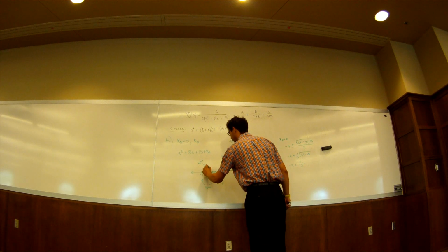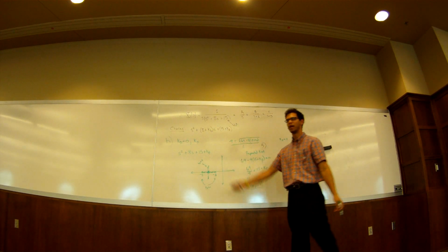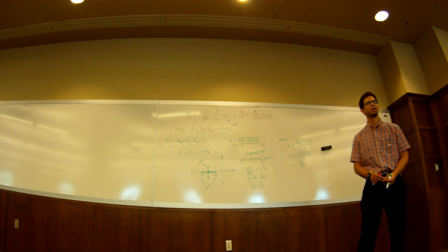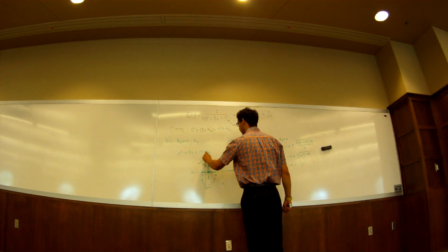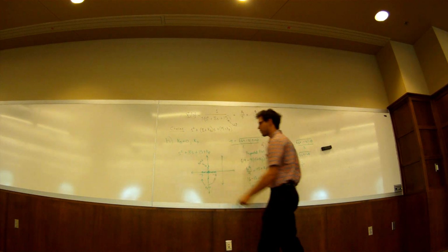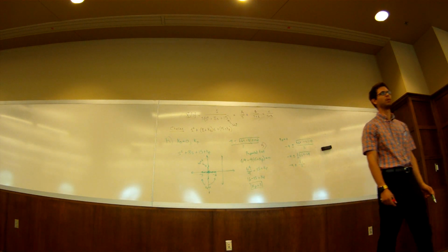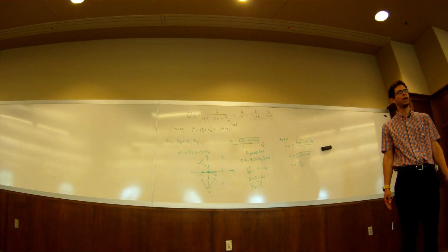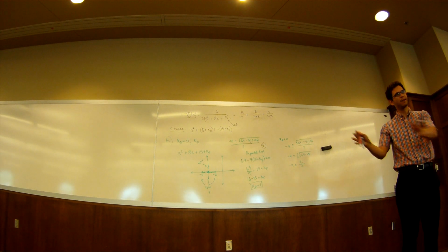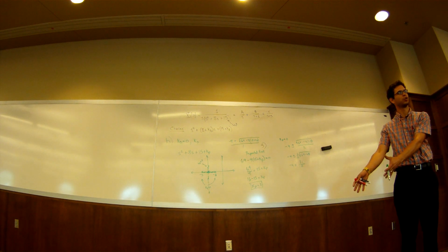So again, my pole did this and this. So what happens when I make Kp even bigger? They're just going to keep going. So my root locus looks like this. Boom, and then boom. Can I ever make this system go unstable by making Kp bigger? No, that's actually kind of cool. So I don't have to worry about Kp. I can make Kp as big as I want. I mean, I have to worry about saturation in the controller, sure.